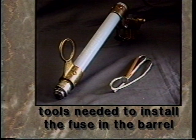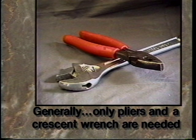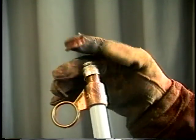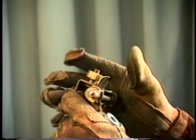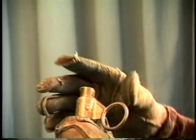The tools needed to install the fuse in the barrel are usually determined by the manufacturer. Generally, to install a fuse, only pliers and a crescent wrench are needed. To install the fuse, remove the cap of the barrel and loosen the bottom nut. Thread the tail of the fuse into the barrel until the fuse head contacts the upper end of the barrel.